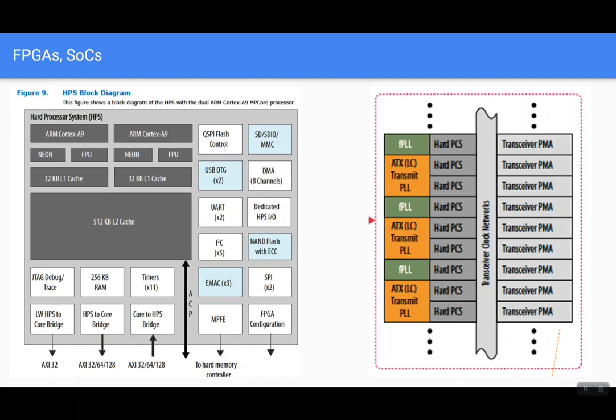A soft processor system like MicroBlaze is all software, which utilizes the logic fabric to be implemented. But hard means that it's already there as a chip within the FPGA or SoC. Okay, so that's what is meant by a hard processor system. Two cores, again, the relevant blocks, and we will go into the details in understanding all the most commonly utilized blocks on an FPGA or SoC chip. Similarly here, as shown before.